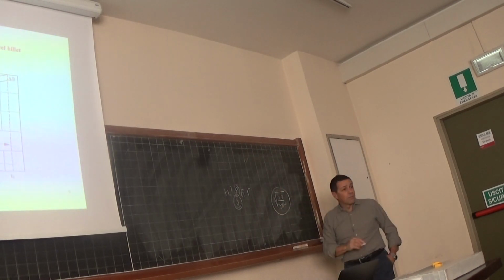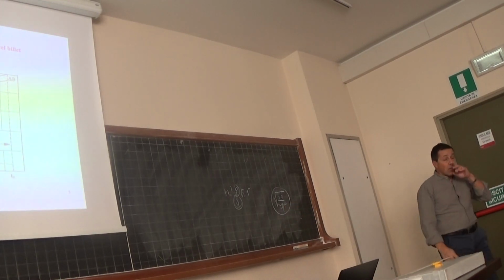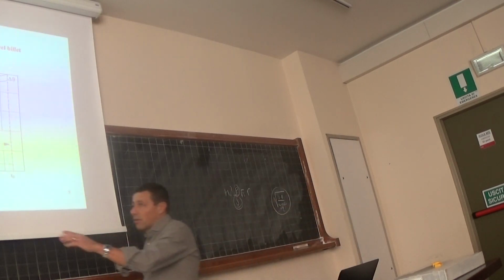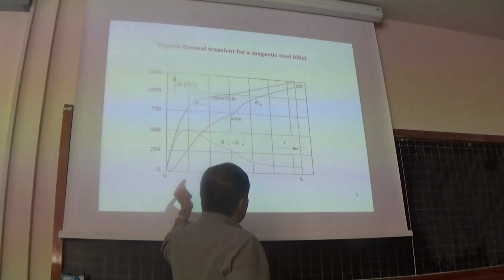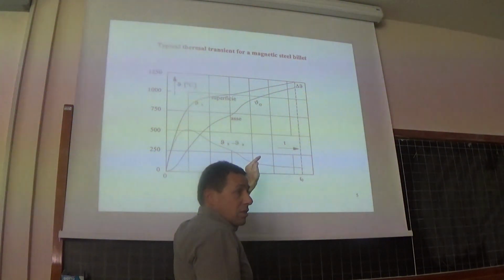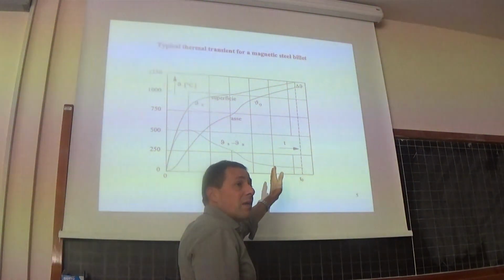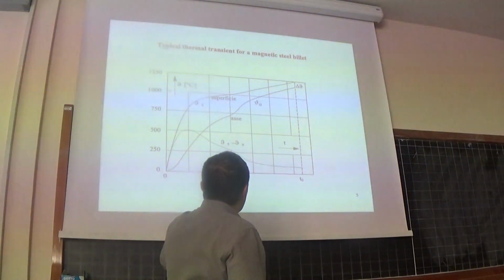this is delta. And you can understand that if the permeability is driving the behavior just below Curie, the main parameter driving the behavior and the slope above Curie temperature is resistivity. Okay? This is the main difference.